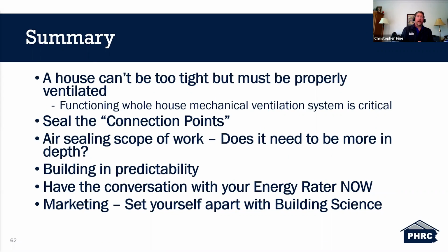Does your air sealing scope of work need to be more in depth, right? Where are you currently falling in? Do you have to revisit that scope of work? Do you have to have a conversation with somebody on staff who is doing your air sealing package? Do you have to pull them aside and say, all right, let's get with our energy rater, run a blower door test, see where we're coming in, walk around with maybe a smoke stick or an IR camera and find out where your trouble spots are, and then address those and see where you're coming in. That way we're ahead of things moving forward.